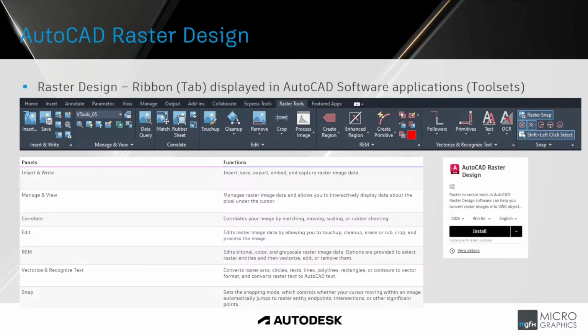Vectorize and recognize text panel converts raster arcs, circles, texts, lines, polylines, rectangles, or contours to vector format and converts raster text to AutoCAD text. And finally, the Snap panel sets the snapping mode, which controls whether your cursor moving within an image automatically jumps to raster entity endpoints, intersections, or other significant points.